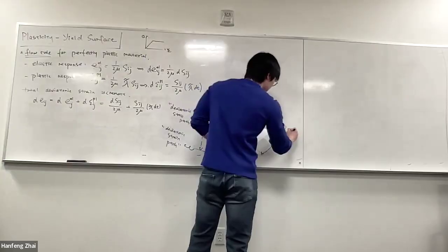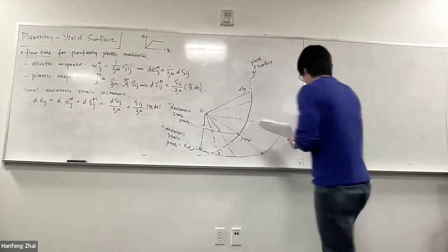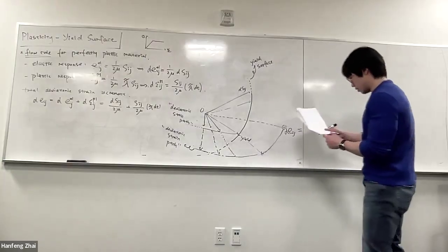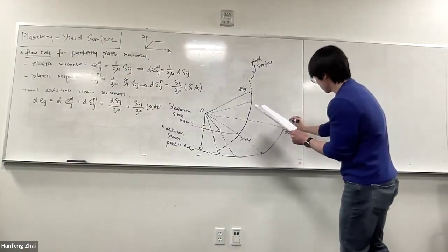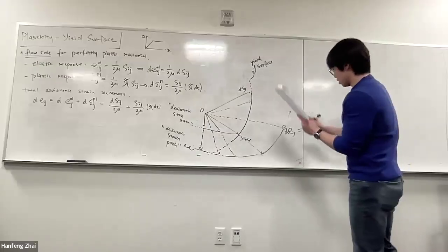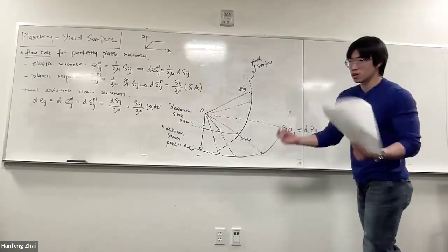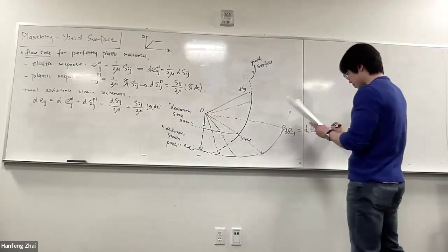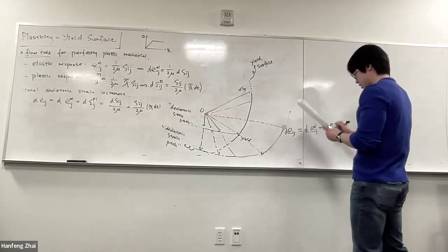So let's say here, the e_ij, well, the algebra by definition, the change or the direction of e_ij, if I were to take a further step, right? Take a further step. de_ij, following the equation we just derived, is the elastic part of the deviatoric strain plus the plastic part, epsilon_ij plastic.